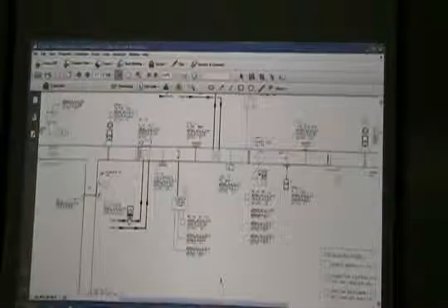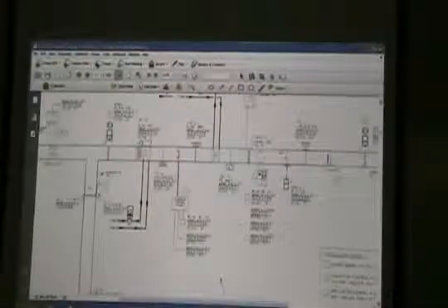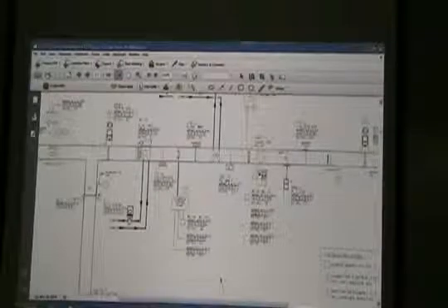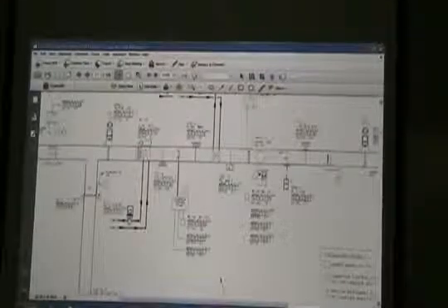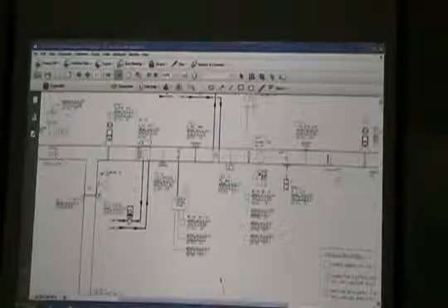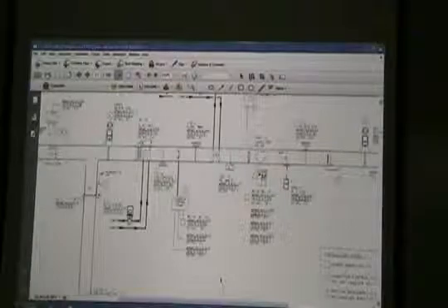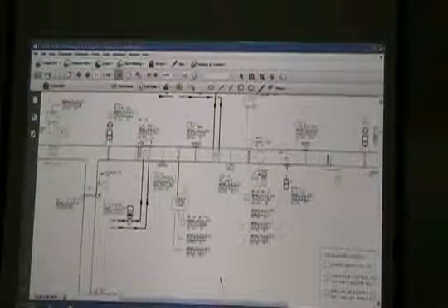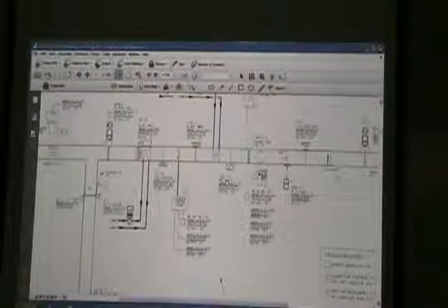Again, you're going to have some stratification inside here, so depending on where that temperature sensor is, we might want to use this temperature sensor to control here, and again, we just move here to get the mixed air. Because you want that air to mix before you get to where you're going to be monitoring it right here.